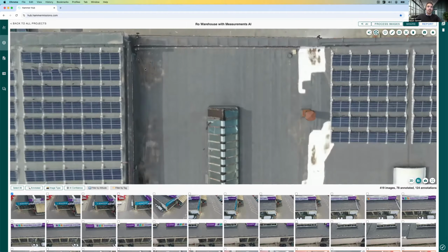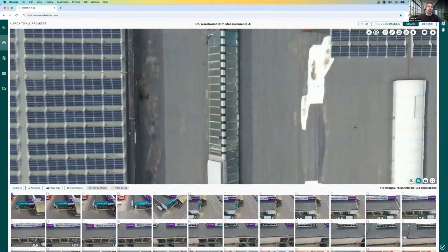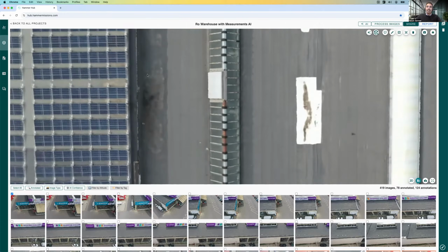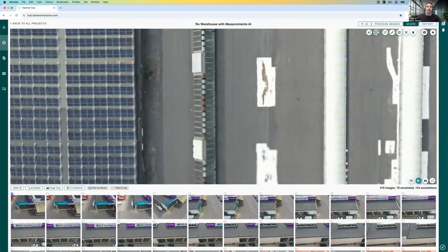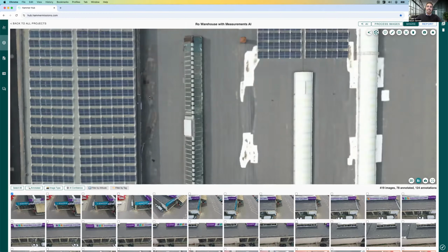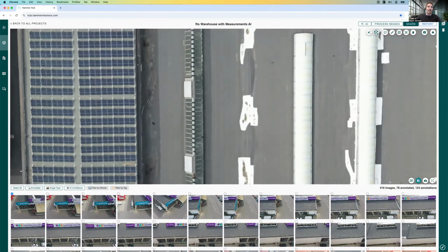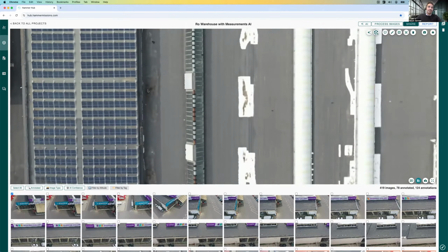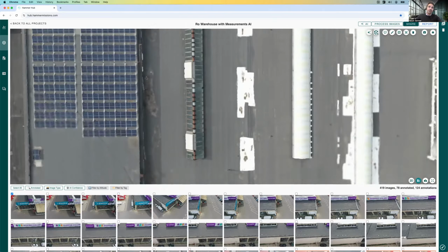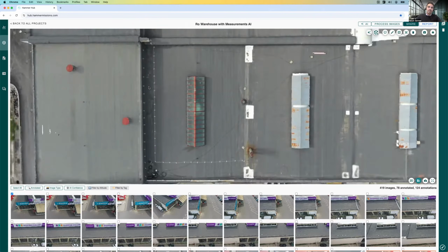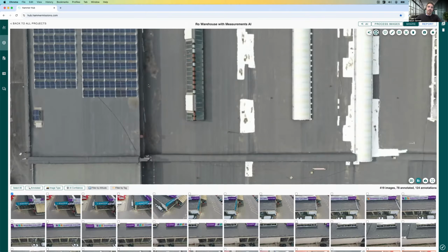So any water that accumulates over here, any pooling or ponding water, would take longer to dry off compared with the rest of the roof. For that simple reason, it stays on the roof a lot longer and causes all these stains that you see. That's a very clear-cut use case where we see all of these different areas of ponding water.